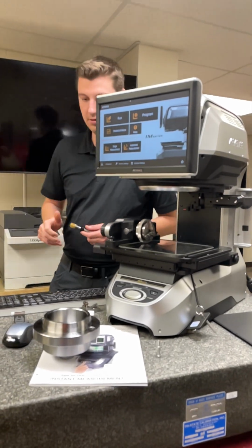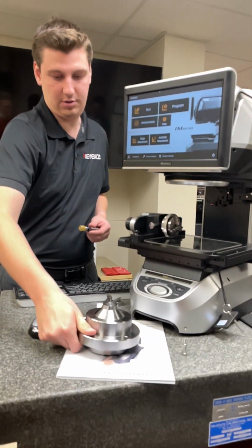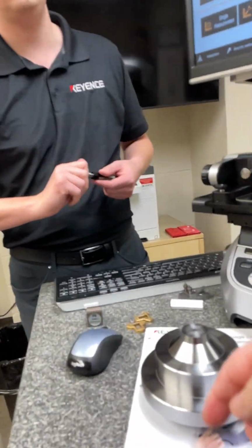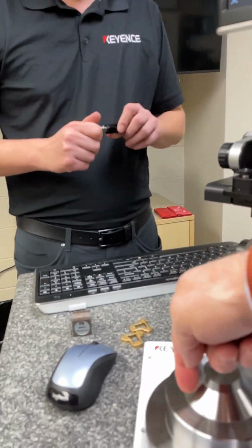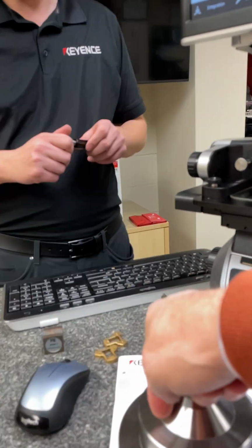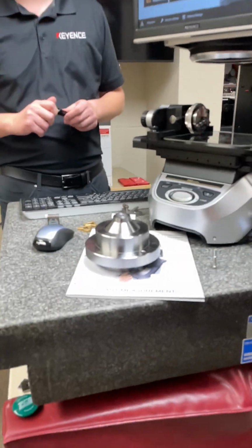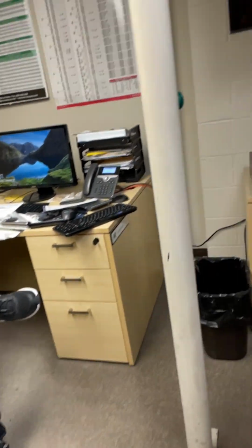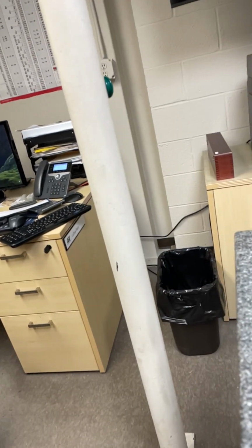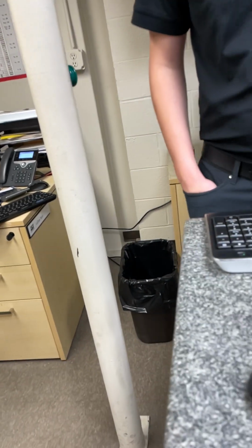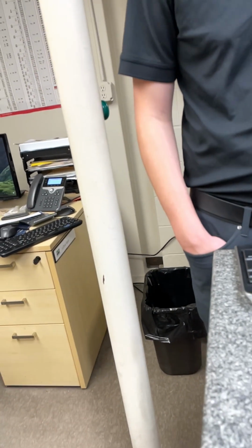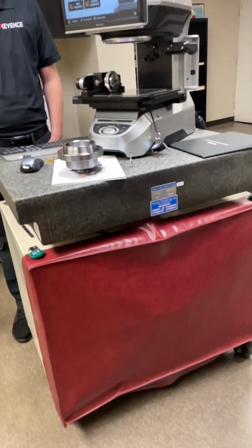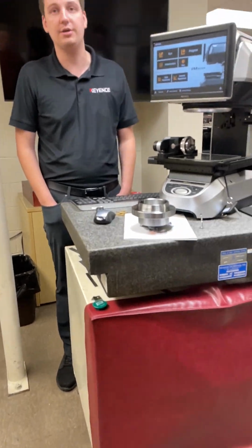So if you wanted, on this part you can do an overall height, step height, flatness. You could not do a point and get an angle dimension. I can do that with the light probe, but it's kind of difficult. I'd rather just turn it on its side and do the line. The reason I'm asking is because if this is flipped over, would it fit down there and measure this angle? No, I don't think it would, to be honest with you. But yeah, the only other thing would be the height gauge.